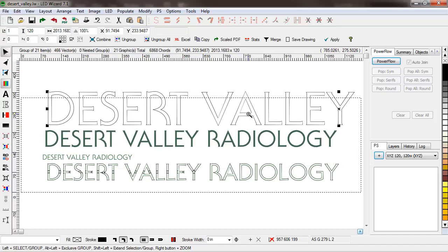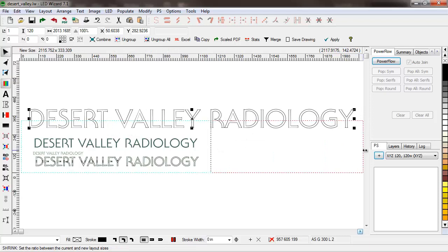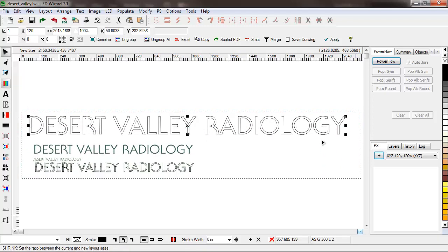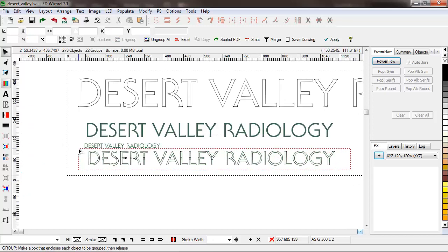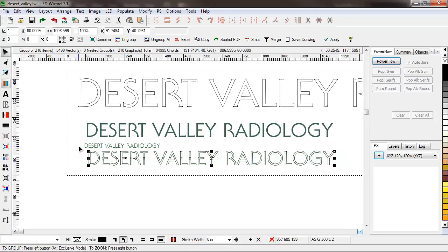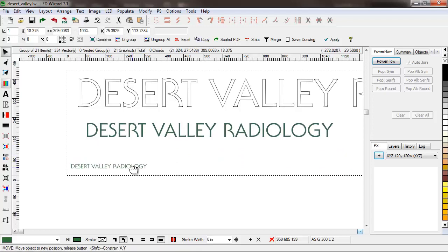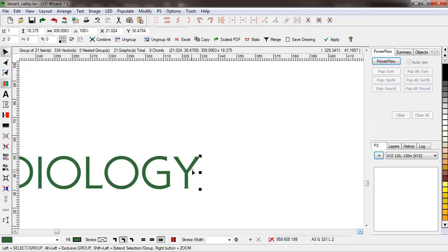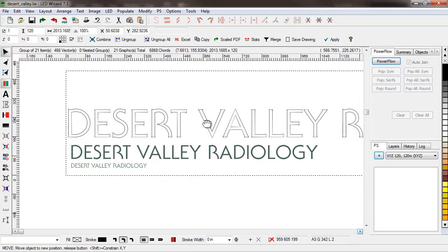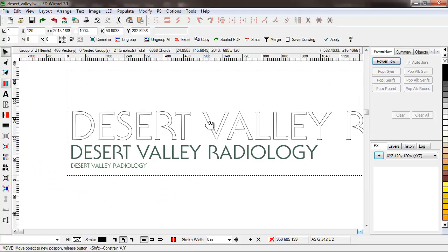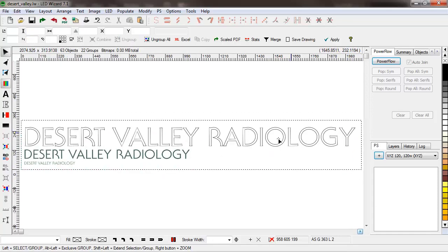And what it does is it actually puts the new size right up here. So I can scale the layout up. And then again, I can go back here, select the original, and delete it. So now in this layout, I have the actual size, 18 3/8 inches, a 60-inch version, and a 120-inch version. And so this is the file that will continue working in this demo.